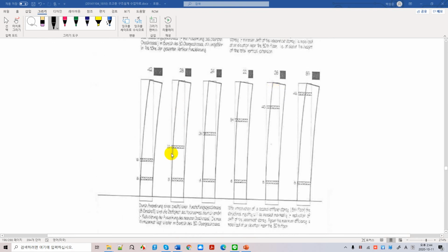Okay, and here is another example when you have two outriggers. So when you have two outriggers and one outrigger is fixed somewhere here, and then you change your outrigger floors and see how your deflection decreases and evolves to a better design. Okay, and you can do the same analysis with 3 outriggers and 4 outriggers. It really doesn't matter, isn't it?